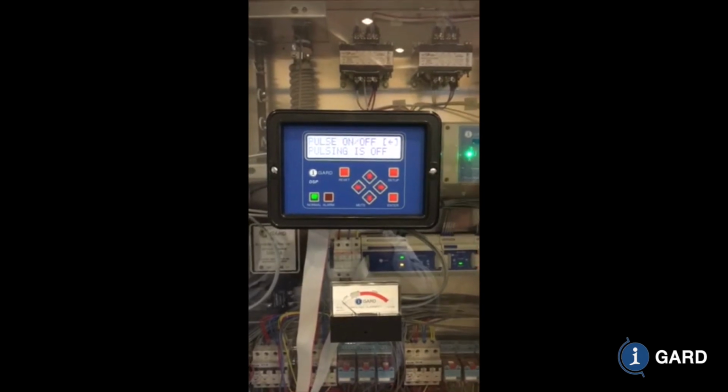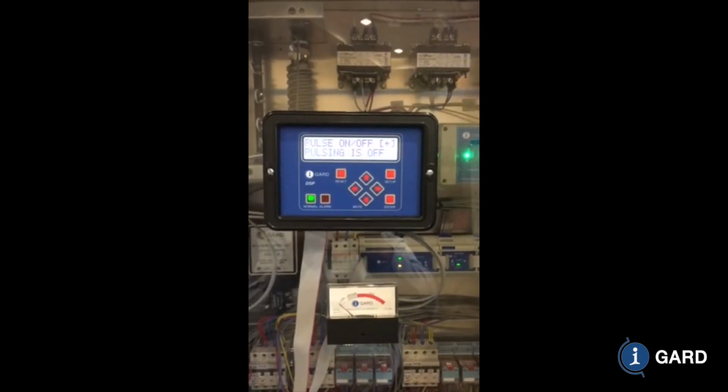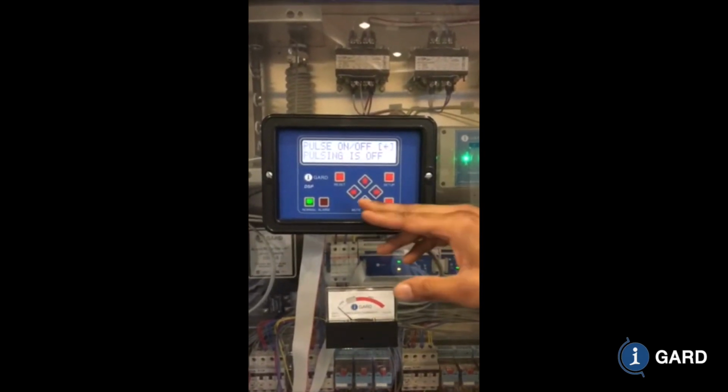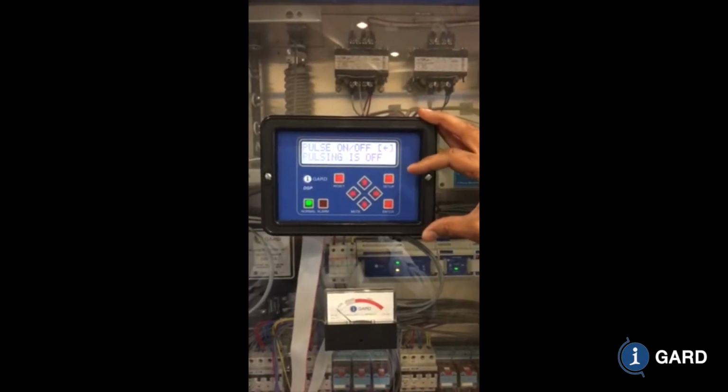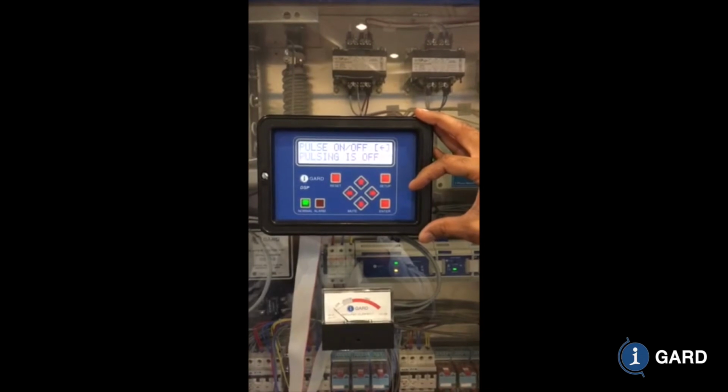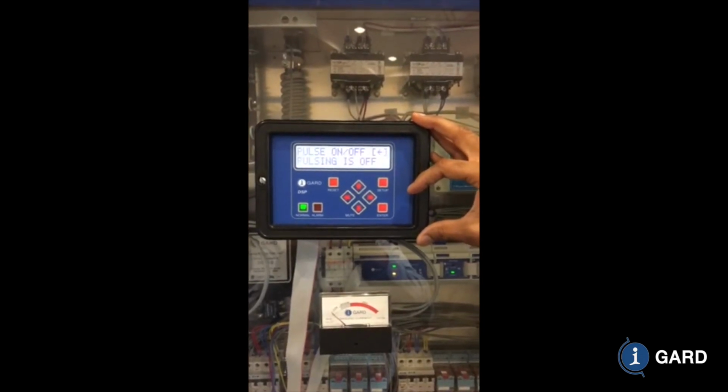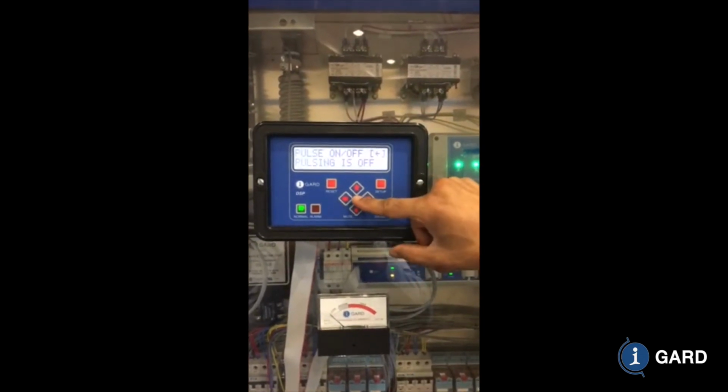It cuts it in half and brings it back from 100% to 50% once a second. So what that does is it creates something to look for in finding your ground fault path. So let's have a look at how that is employed.